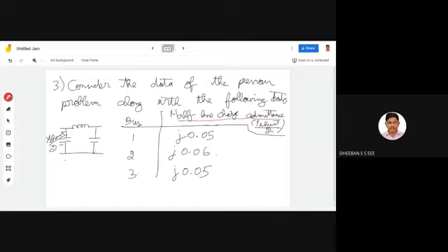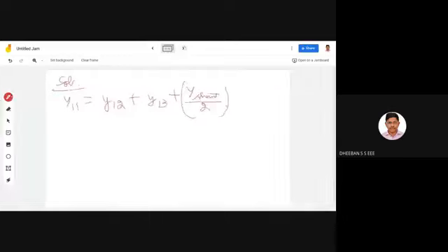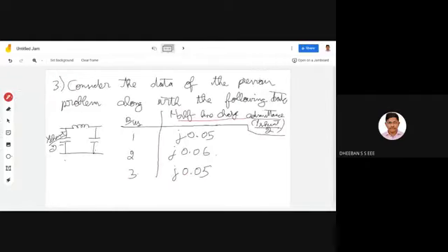What they will be simply giving is the offline charge admittance value. Then you have to consider this to be y shunt by 2, and this y shunt by 2 you should not again divide by 2.